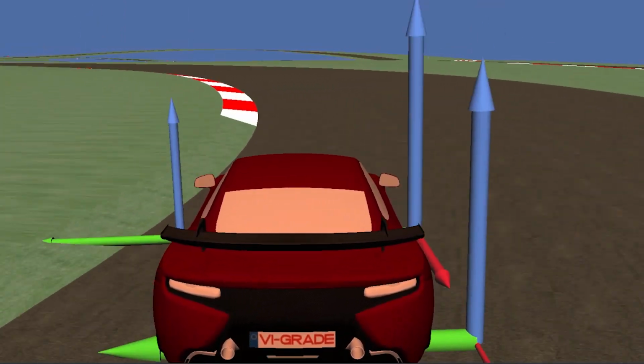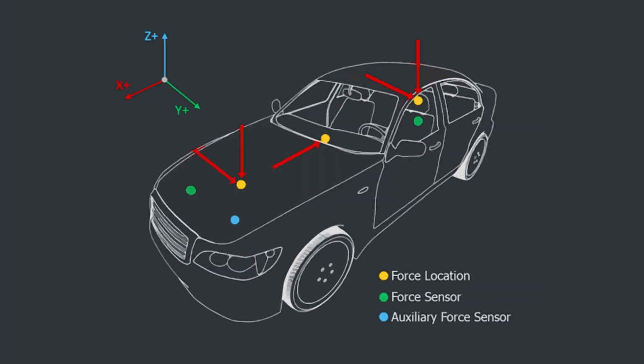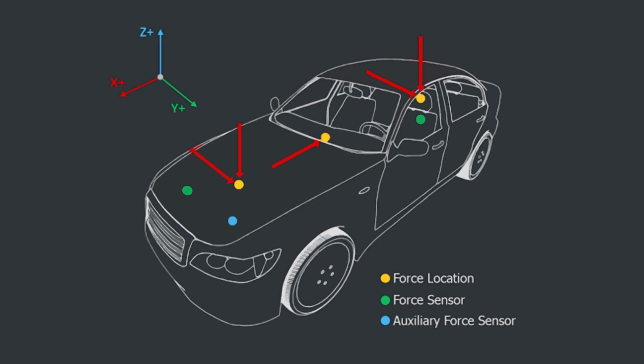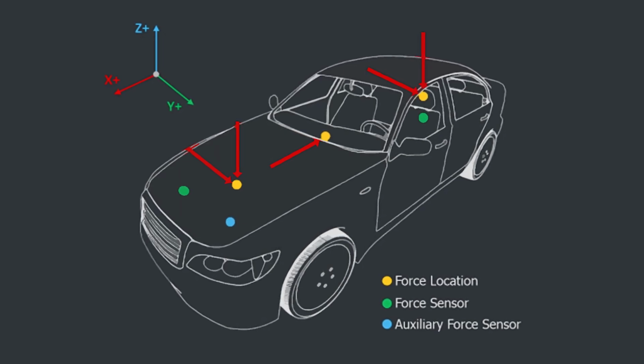For that, we're going to run a series of maneuvers allowing us to quantify comfort and vertical load consistency on the tire contact patch. We'll then analyze the compromise between these different characteristics and further develop our dampers. We'll start the process installing extra sensors on the vehicle, allowing us to quantify these characteristics. Then we're going to learn how to create custom road profiles. And finally, we're going to run maneuvers to quantify ride and comfort behavior.